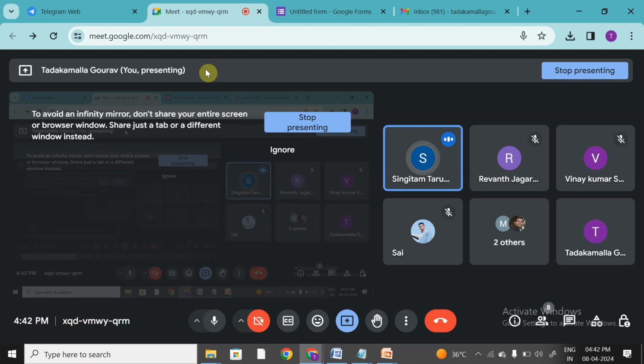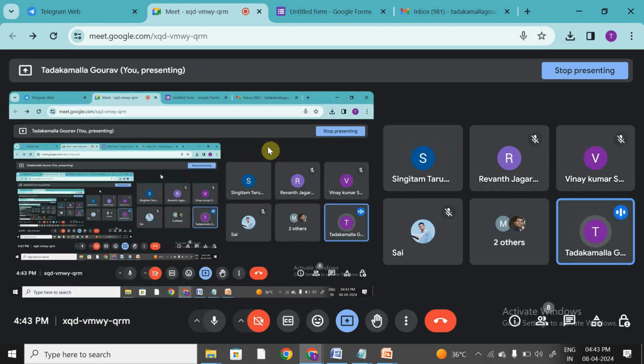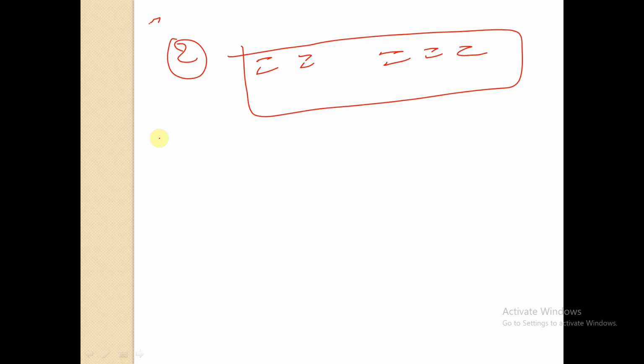I have one doubt in case. Will the control go sequentially or parallelly in case? Parallelly. It will compare, and if it finds anything matching, it goes there. For example, if we write case A, and A is a register of 2 bits, reg [1:0] A, that is A can hold 2 bits.